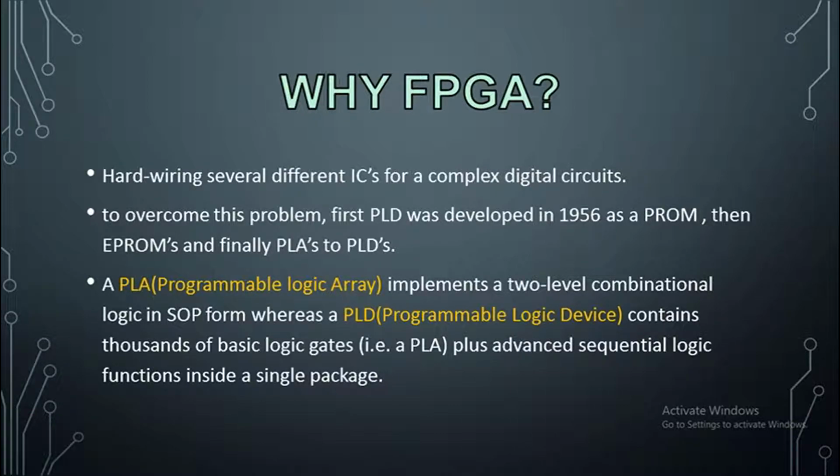Like you have to take an AND IC, OR IC, NOR IC to implement a very basic 2-level or 3-level combinational logic circuit. So hardwiring several different ICs is a very complex process, and another disadvantage is that it requires an excessive amount of area on a PCB, consumed by requiring several different ICs for each logic function.